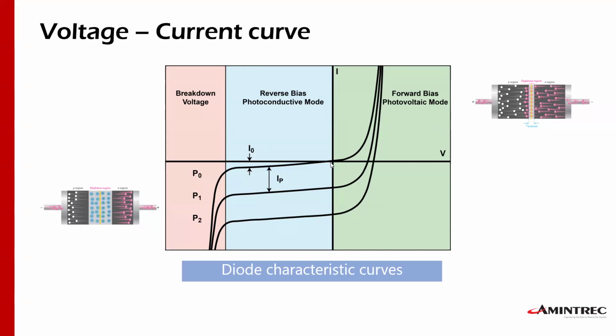If I have that, I'm on the X and the Y axis, and I have a very small amount of current called the leakage current. Like I said before, this is in the range of microamps. But once I reach a certain voltage, called the breakdown voltage, the current just goes up very fast, and we have a lot of current, even when it's reverse biased.